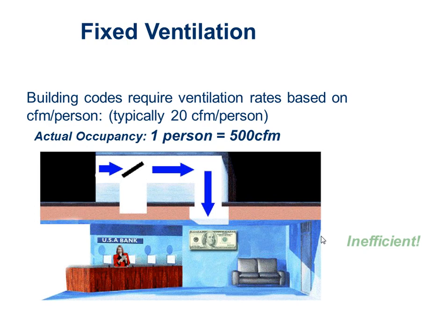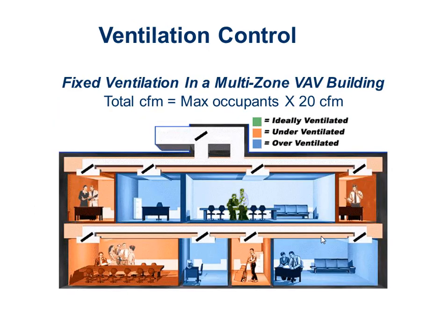So what we want to do is find ways to reduce this outside air. Zoning systems have a similar scenario. We have a fixed amount of outside air coming in at the outside air handler, and there are 2 problems with this scenario. One is, on many of these systems, we have variable frequency drives on the fan, and as those fans slow down, our fraction of outside air changes significantly, and we are bringing in more or less air than we had originally planned.